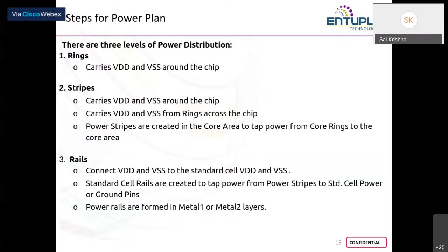It is just like parallel corridors in a building, but the only thing is, instead of running parallelly in the same direction, every alternate metal will run in perpendicular directions. The gap between them is covered by vias, which stand like the staircase between two floors for connection.